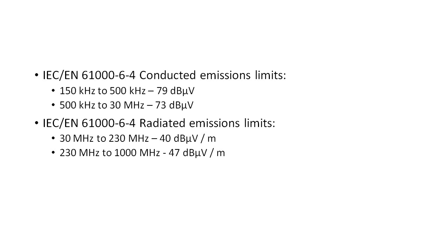Now let's go back to the dilemma posed by my example of the insulation monitoring relay. It complies with EN 61000-6-3. The NRC requires compliance with IEC 61000-6-4. The question asked was, does the equipment as tested comply with the NRC's emissions guidance?